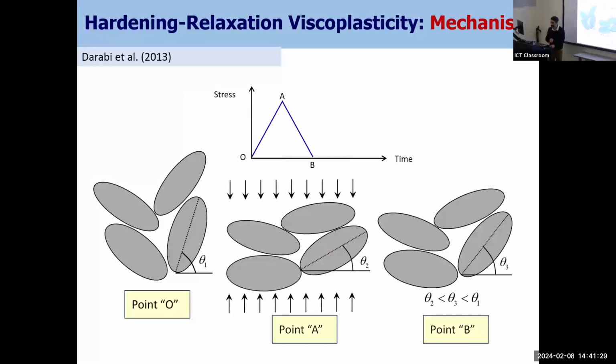Yes, but I was just curious, what are the test parameters that are required? Some of the details to define that memory surface, what are the requirements? So the test that we use is a constant loading time and unloading time test. So it is creep recovery, and we look at the progression of the plastic strain. Obviously, when we use the model without the memory surface, it just saturates, and then by analyzing those, we can get the model parameters. I hope I answered your question.